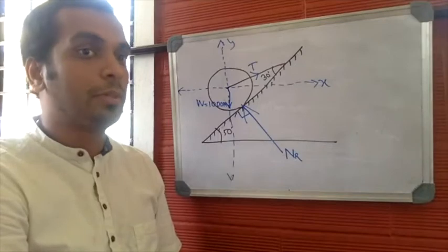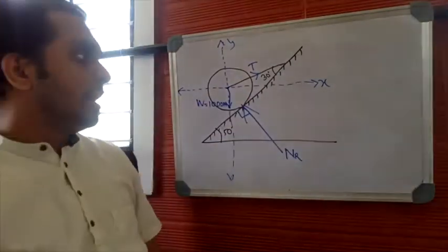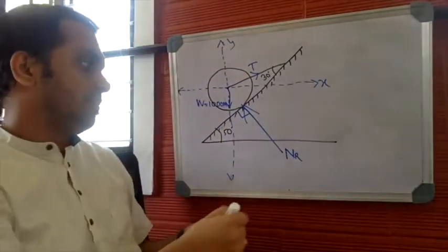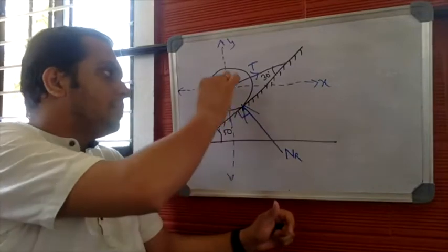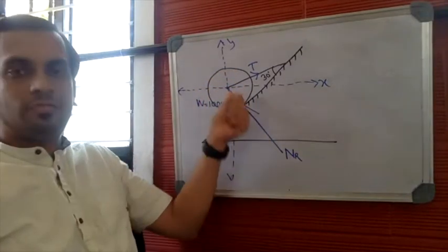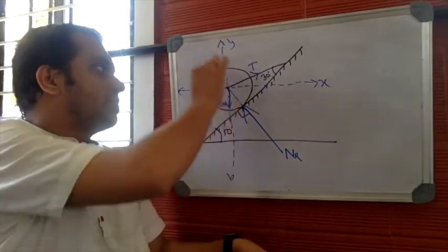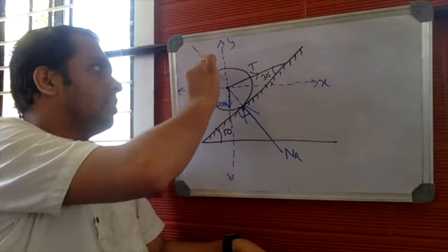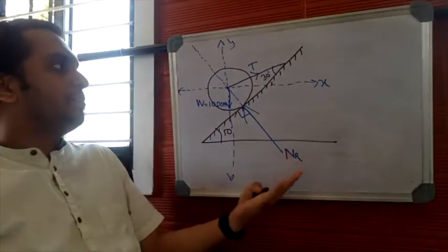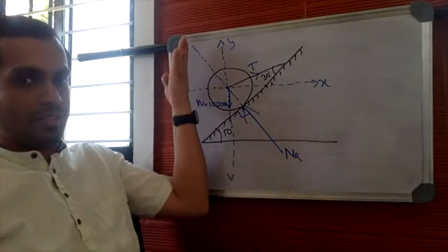In the next step, step number 5, we are done with step number 4 as far as drawing the free body diagram is concerned. Now let us rearrange. I'll just rearrange it here itself in the question. The original position of the normal reaction is in the 4th quadrant, if I'm not wrong, right? I'll draw the line of action of the normal reaction. You can apply the principle of transmissibility and push this normal reaction to the 2nd quadrant.